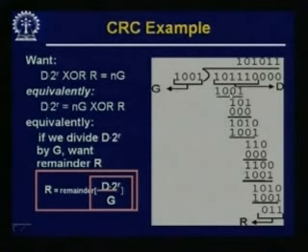So, 1001. Only thing is that where we usually subtract, we do a modulo 2 kind of operation. So, 1 1 gives 0, 1 0 gives 1. So, we got a 101, then we got a 0 and so on. This way the division goes on till we exhaust this, and we get as the remainder 0 1 1.